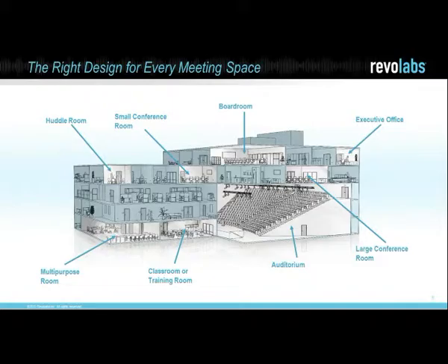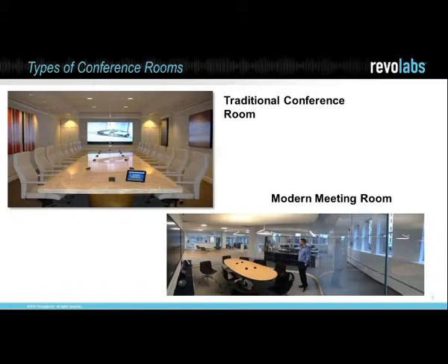Well, the next slide does present two pictures here, one of what you call traditional and then what I would call the modern room. What's different, changing over the years from the traditional to the modern rooms? Well, unfortunately, as we move forward, people are kind of forgetting some of the importance of the basics of room design and going with what's more of a desire for some other reasons. For example, people are liking transparency in the workplace, so more and more rooms are becoming glass or transparent conference rooms to show that sort of thinking. But these rooms are very, very bad for the acoustics, and we can talk about that a little further.